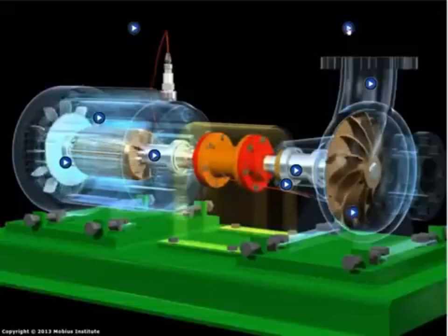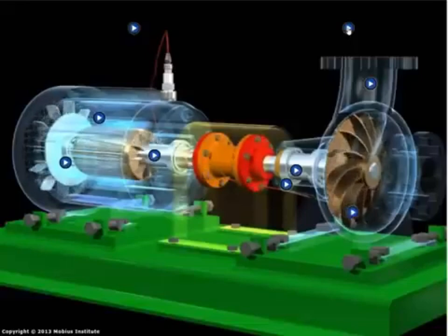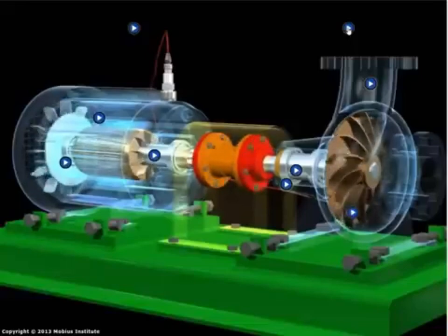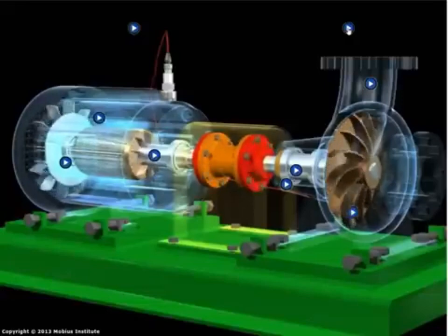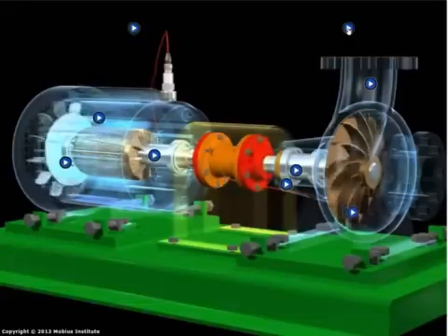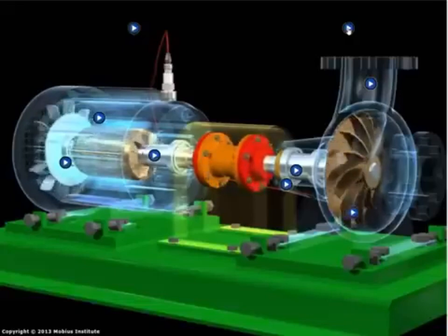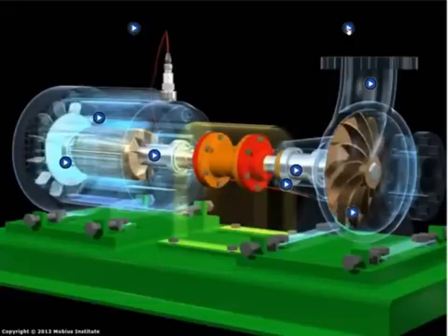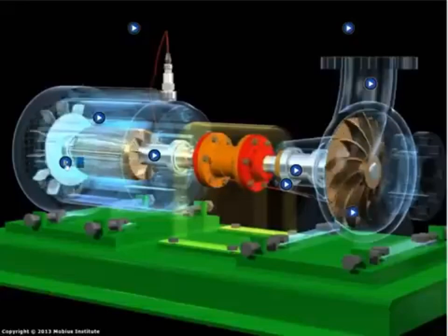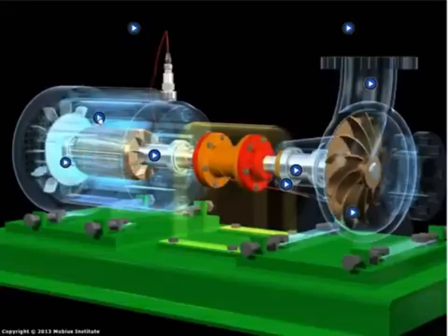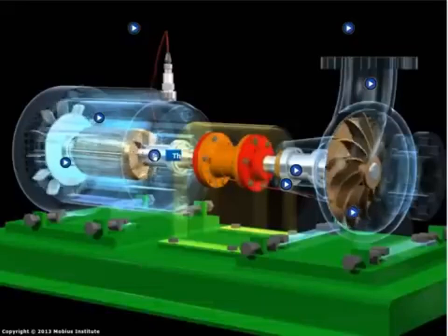But what vibration analysis allows us to do is break that sound up into all its individual components, because those individual frequencies actually relate to different components within the machine. And as those frequency components change, it provides an indication of whether there's a problem with the bearings or the rotor bars or the shaft, which can be misalignment, unbalance, or anything like that.